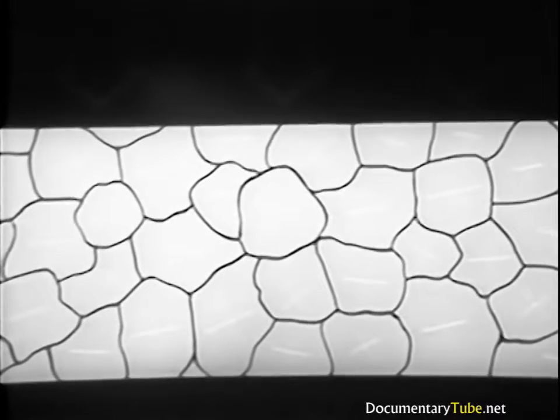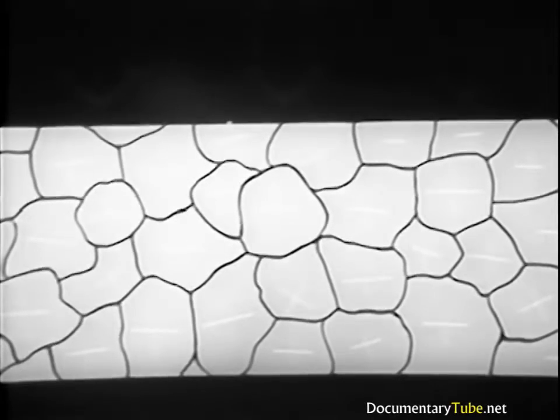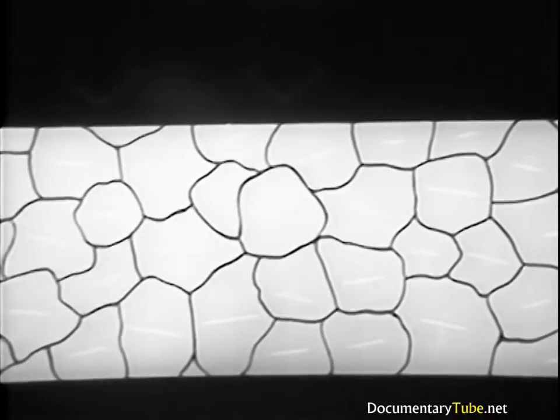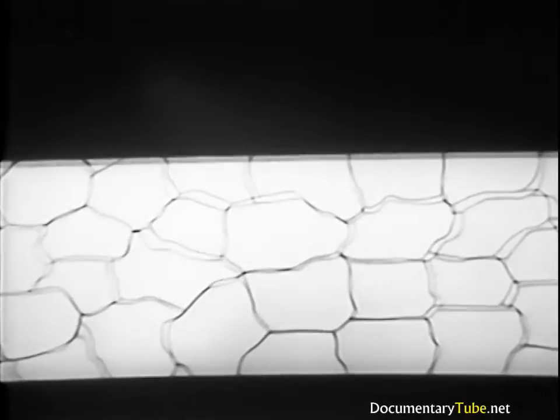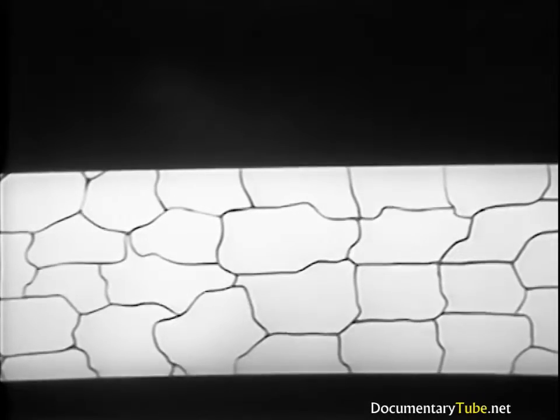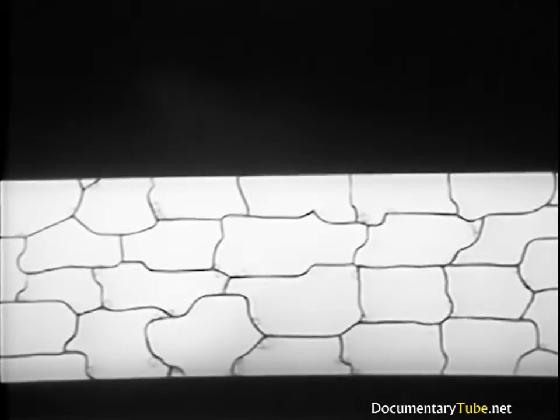Under the type of load applied in the bending and stretch forming processes, the grain structure of the aluminum alloy changes in a manner similar to that shown for the cold rolling and stretching processes. The grains rotate along the active slip planes and become elongated, and the metal is strain hardened. The cold working involved in the hammering, hydropress forming, drop hammering, and deep drawing operations results in grain rotation and elongation.